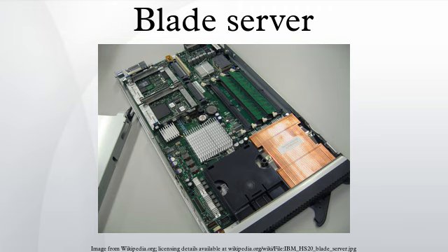History: developers first placed complete microcomputers on cards and packaged them in standard 19-inch racks in the 1970s, soon after the introduction of 8-bit microprocessors. This architecture operated in the industrial process control industry as an alternative to mini-computer control systems. Early models stored programs in EPROM and were limited to a single function with a small real-time executive. The VMEbus architecture defined a computer interface which included implementation of a board-level computer installed in a chassis backplane with multiple slots for pluggable boards to provide I/O, memory, or additional computing.